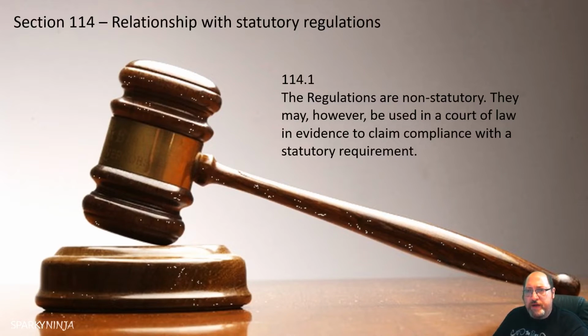Very, very popular hospital in the Crowthorne area, and we had to install some socket outlets at extra low voltage, and then we ended up having them changed from PELV to SELV, so we had to have them electrically separated, due to the fact that these patients required access to power in their rooms, but they were vulnerable to their own actions.